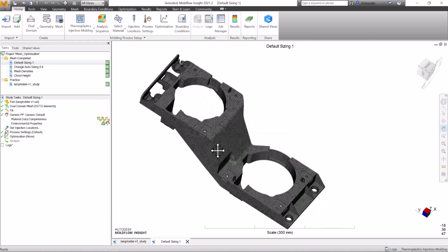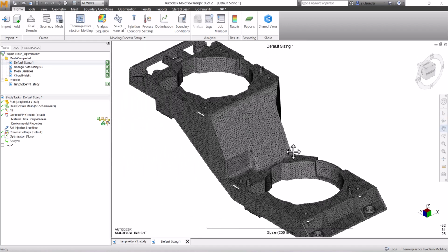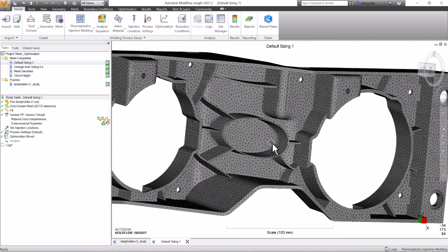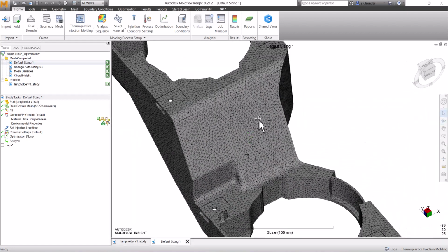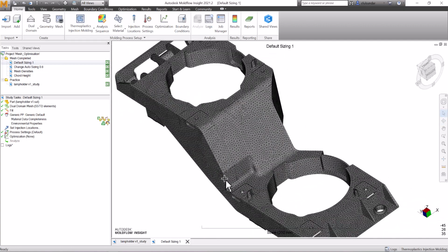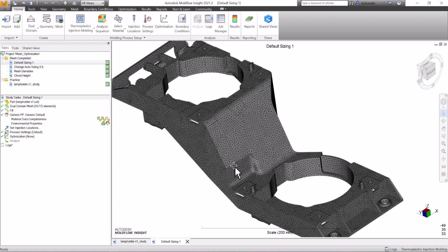Pretty much it has created a nice mesh, and of course the feature that is on the back side is also getting imprinted over here. So I'm going to get a sink mark, or the impression of the sink mark, nicely if you have this mesh match ratio, or the matching of the elements from the feature on the other side.